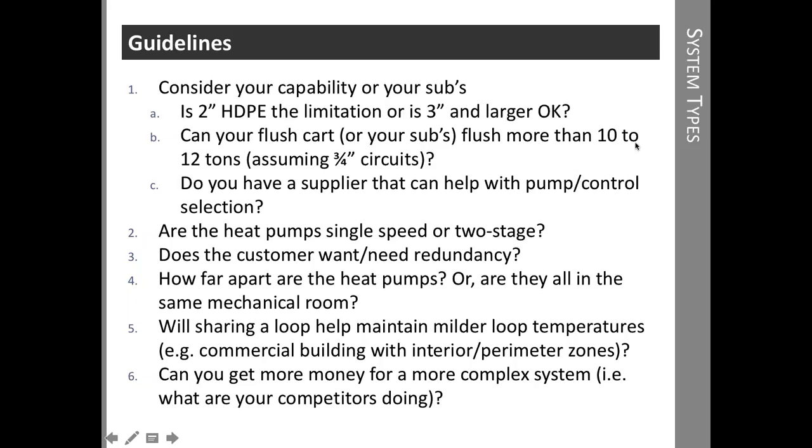Another limitation could be the flush cart. Most residential flush carts are designed for 10 to 12 3/4-inch circuits. So if we're looking at 1-inch circuits or 1.25-inch circuits, we have more than 10 or 12, so we have to be a little bit cautious there. There is a calculator on Geo-Flo's website that will determine whether or not you can flush that loop with the Enertech flush cart. And the C here, fortunately, is not an issue with Enertech, since Enertech has an inside support department, inside sales. This is a big deal.